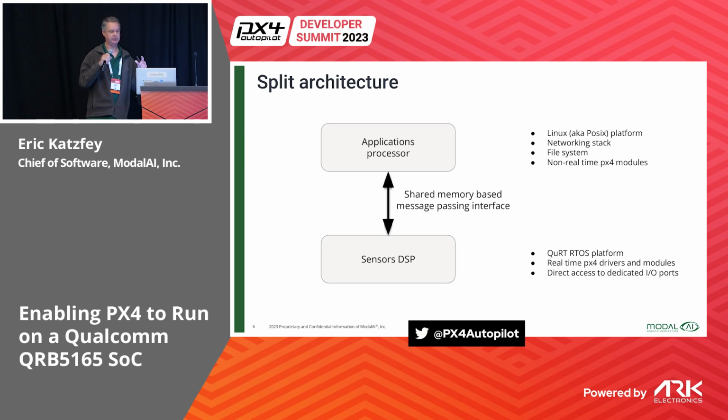That's the applications processor, and inside this system on chip device, there's a bunch of other DSPs and GPUs and things. One of them is referred to as the sensors DSP. This is a Qualcomm architecture called the Hexagon architecture.